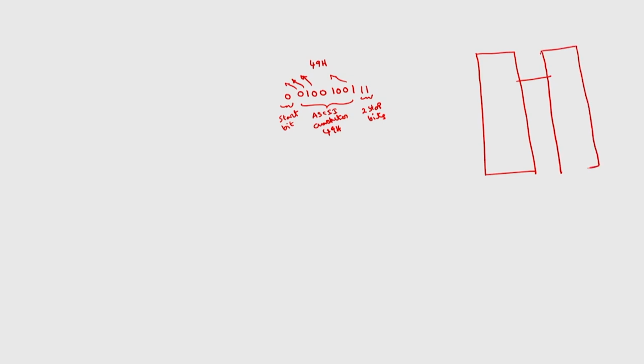So, how to write the program for this? We have connected this microprocessor to port A of the 8255. This is the serial data pin. So, inside this 8255 we have this serial data pin. I will connect it to port A, the output port. Port A of 8255, I will program as output port, say PA0. This is the microprocessor.